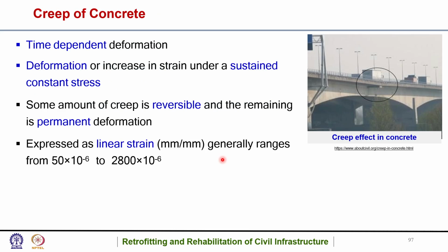So then, let us go to the next important topic, that is creep. Creep of concrete. So what is creep basically? Creep is basically the time dependent deformation, or increase in strain under a sustained constant stress. Some amount of creep is reversible and the remaining is permanent deformation.